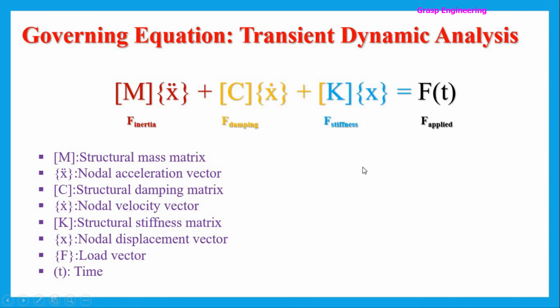Once you satisfy the inertia, which you get once you apply loading, the damping, which you need to define, either structural or material damping, and the stiffness, which the model considers with the help of the defined geometry and material, you will get the time domain response for the applied time domain load.